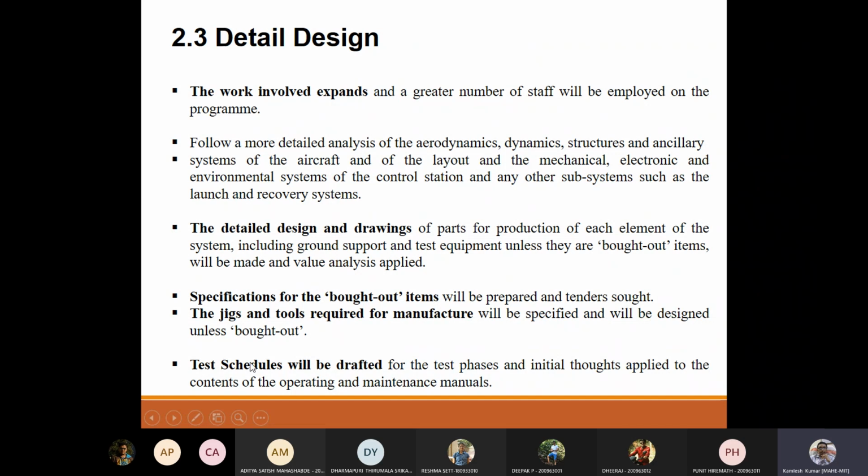So you should then have test schedules, especially for the technical products that should get tested, for various types of tests, not just flying the model. If you want to test the communication system itself, you have to test the whole aircraft in the hangar, correct, where you will see equipped chamber type systems. If a system should be tested at the acoustic level also, you should have an acoustic chamber, correct, where you test that communications will not get affected, because you will see lots of sound.